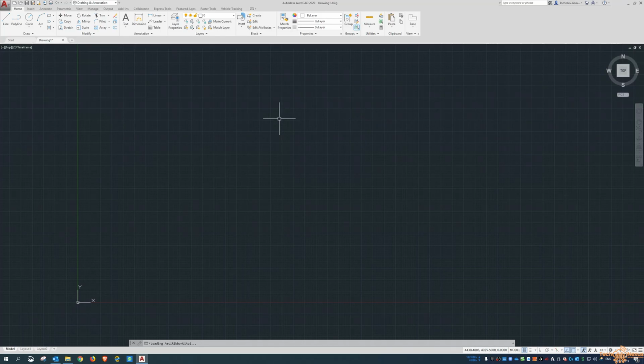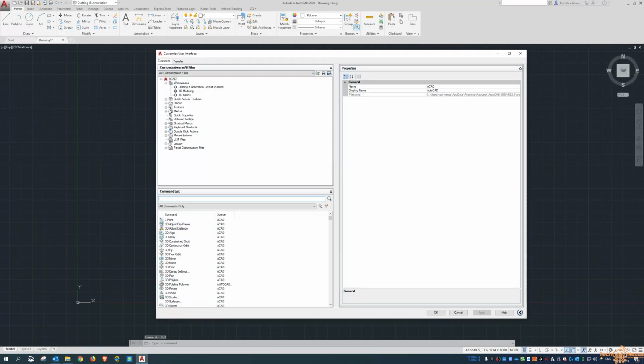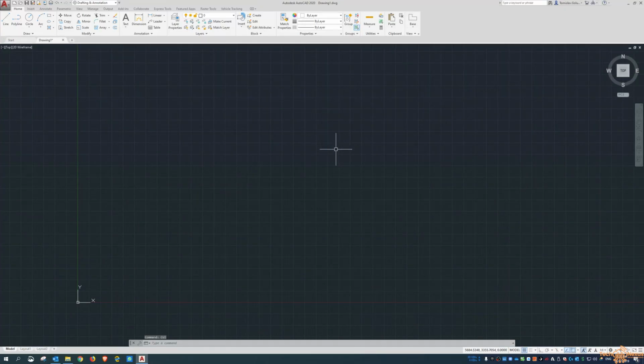There are toolbars still. So for the more seasoned users watching this video, the toolbars are still there, but they no longer have labels. So it's going to be kind of hard to see what toolbars you have and want to use, and I think that was a reason why a lot more people use the ribbons and the palettes these days, just because toolbars have gone the way of the dinosaur. They're still around. If you type in CUI, you will see functions there for toolbars as well, but again, I haven't seen people use toolbars for years.